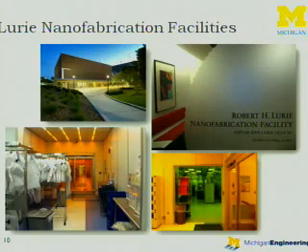In the picture on the bottom right side, you can see the whole room is yellow. The reason is that there's no UV light in the clean room, and that's why the whole room is yellowish in color. This is to prevent the UV light from destroying your device.